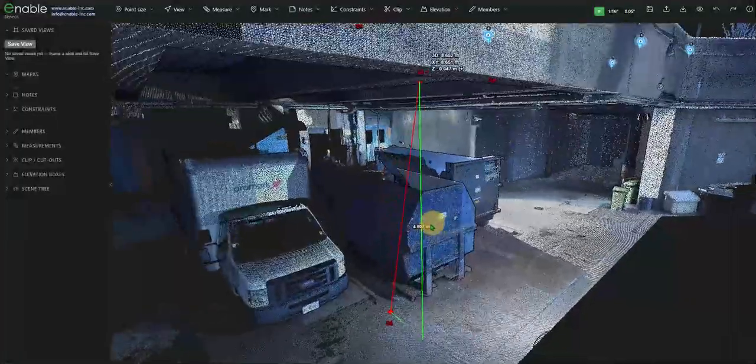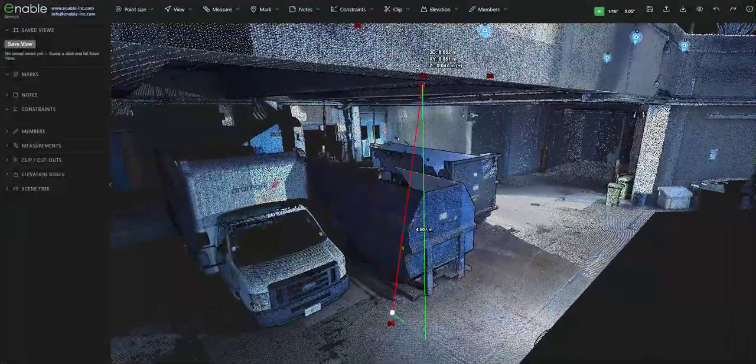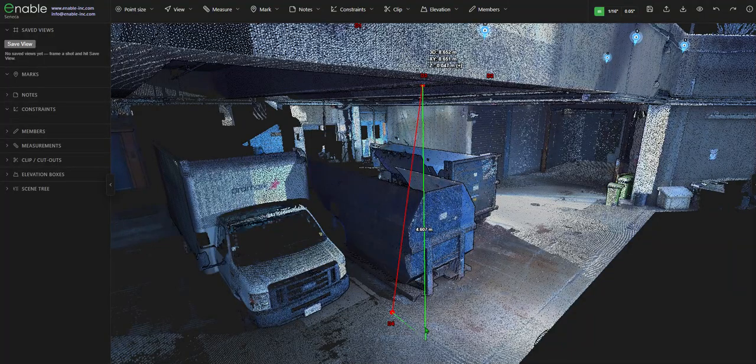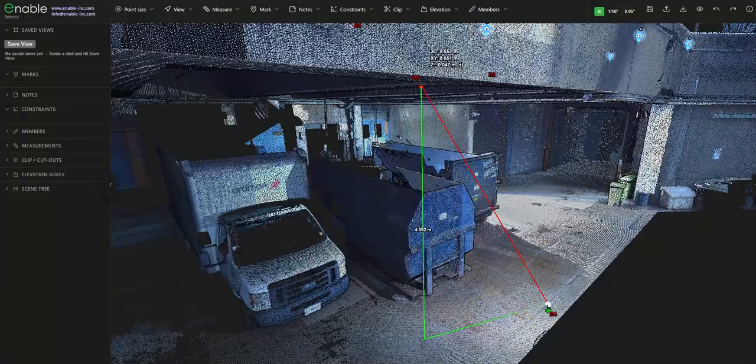The great thing about this particular tool is that it doesn't have to be directly aligned with the first point because of this projection. So, for example, if we put this point and drag it by left clicking all the way over here, or now I've snapped it back to this particular line, you see it's fairly close to what it was initially, because the projection goes right back to the first point, and that projection is in the Z plane.